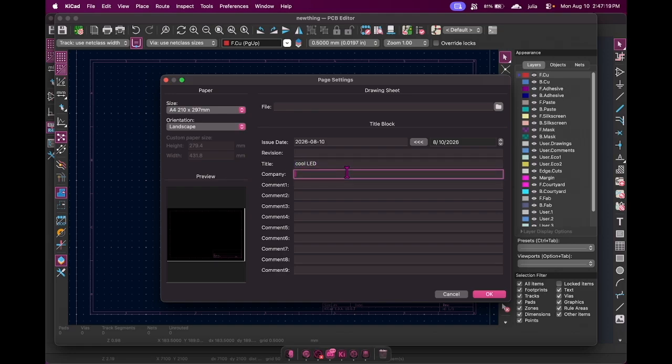That's a big number. Are you running the DRC? I don't know. There's an ERC which is in the schematic and then a DRC which is in the PCB editor. The DRC is design rules, like is everything arranged in a nice way? I think it checks for some electrical rules too, like if there's a violation in how we're wiring it, but it's more about the design because that's what you're doing in the PCB layout. I'm gonna put my name here.